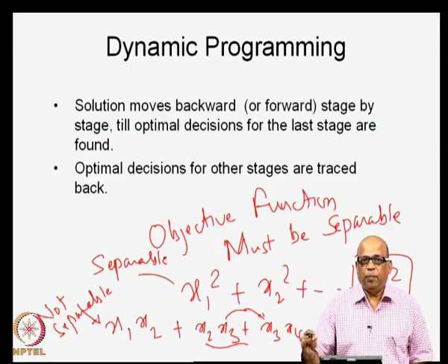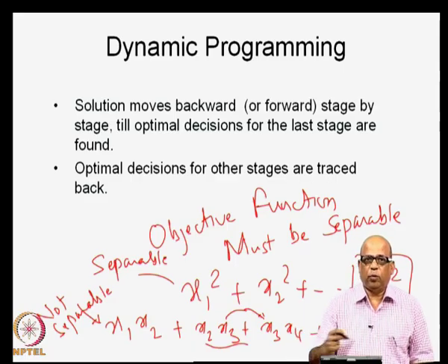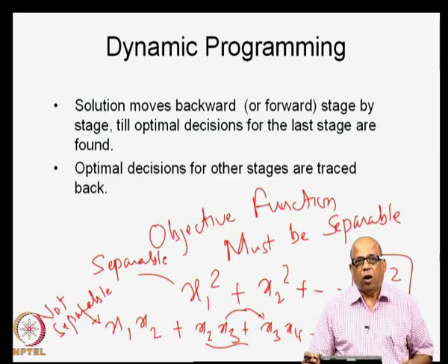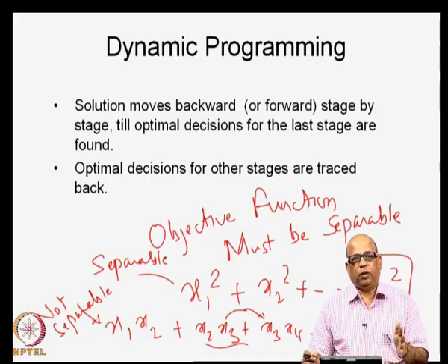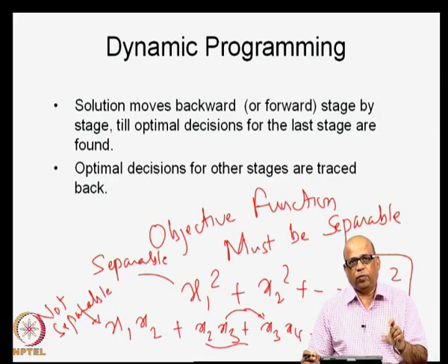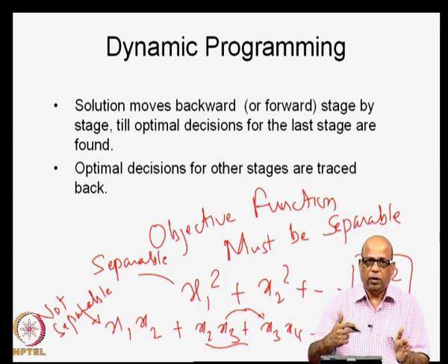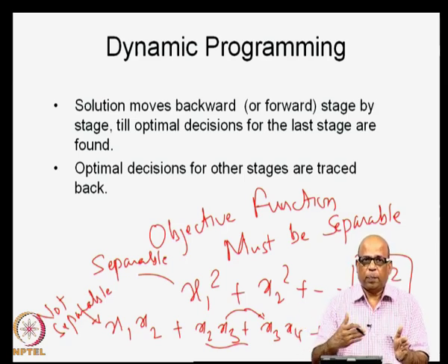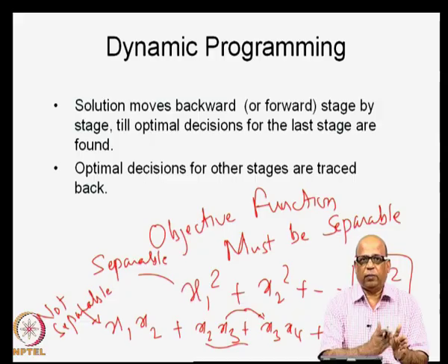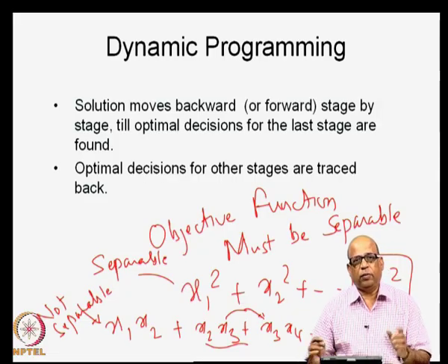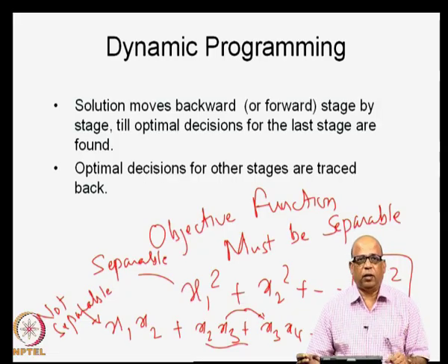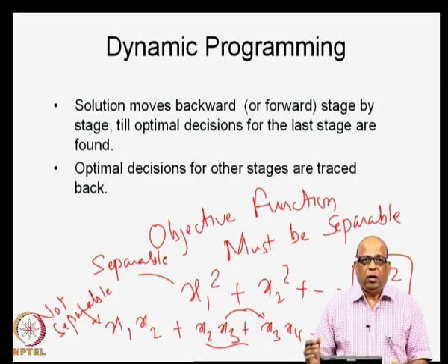So, that time period boundary conditions may be known, and then starting with that you may proceed backward, or your initial storage condition in the case of a reservoir operation problem may be known, in which case you come in the backward direction, and then when you do the last stage calculation, you will use this as a condition that needs to be satisfied.